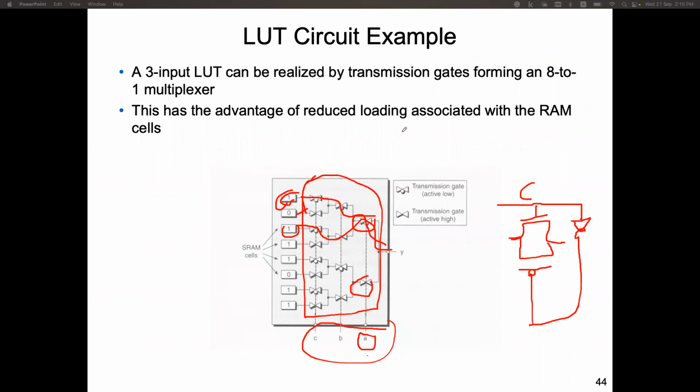Okay, I think time's up. We'll stop here. So today we introduced this simple but very fundamental, important concept in FPGA implementation: the lookup table. We store some data in a small block of memory in each cell, and we can program it. We can write right into those memory locations.